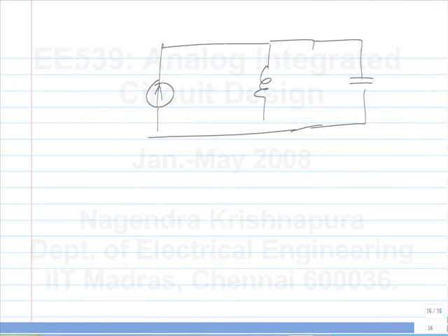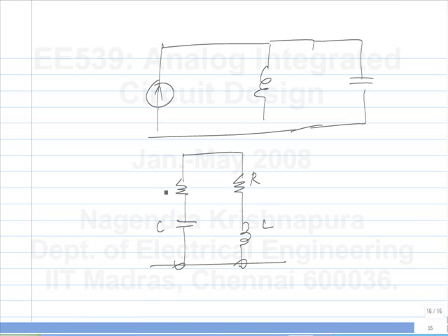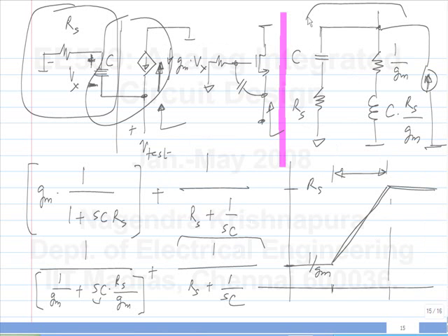Let me ask you something else. Exactly. That's the reason that I was in fact going to ask what happens in the general case. It is a second order system, but there are two time constants associated with this. C R1 is one of them and L by R2 is the other one, and they are the same in this circuit. So you have a sort of pole zero cancellation. If you write it in terms of general values, you do get a second order system. But in this case, it's effectively restating that the inductance is generated by some control source.